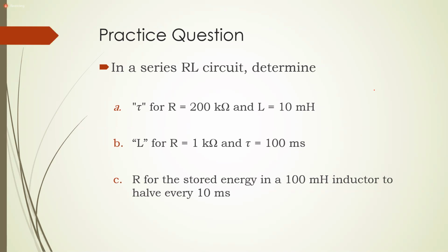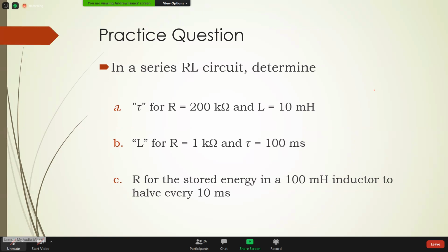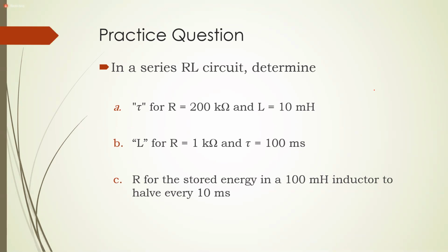But anyway, let's think about power. We know power equals I squared R. Everybody agree with me? Yes. So if R remains constant and I reduce the current by a factor of a half, what would happen to the power? It reduces by a quarter. So how is it that the power would be halved? What factor must the current be reduced by?